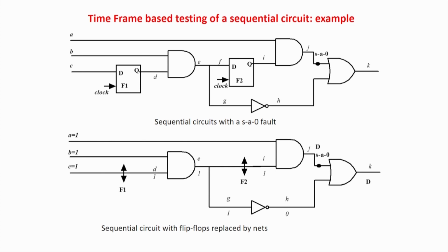Now, what if I use a scan chain? Scan chain will solve your problem, but still the time taken will be very, very high. Scan chain actually solves the problem in a very indirect manner. As I told you, there are two ways of optimization, if you have seen my lectures on ATPG in this module: how difficult it is to generate the test patterns and how difficult it is to apply them. Scan chain does not actually help in reducing the test application time.